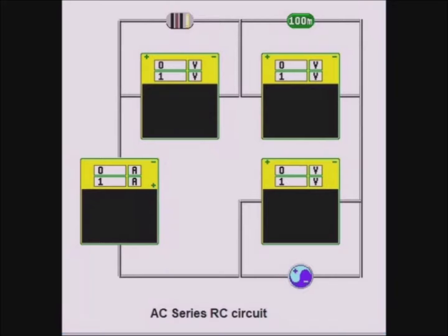We introduce alternating current with a resistor and a capacitor. There are a few things to notice about the waveforms created here. Firstly, if the capacitor were not there, because we have a 1 ohm resistor, the amplitude of the current would match the amplitude of the generator and they would be in sync. Secondly, because the current amplitude is less than the generator amplitude, the capacitor must be impeding the current.